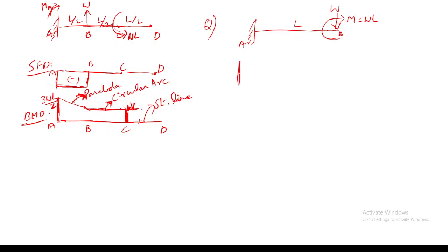We are going to split this beam into two different loadings, since we have no formula for the combined loading, whereas we have the formulas for the individual loadings of the point load and the bending moment.